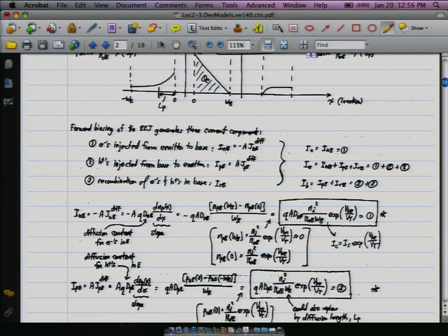So I may go in one direction or the other, just depending on what seems more clear at that point. But basically, the way that we can start to break this down is we have the base current right here, and we can split that up into basically the current density and the cross-sectional area. Because if you just size your device differently, you have a larger device, you'll have a larger current. So we like to get that factor out before we start.